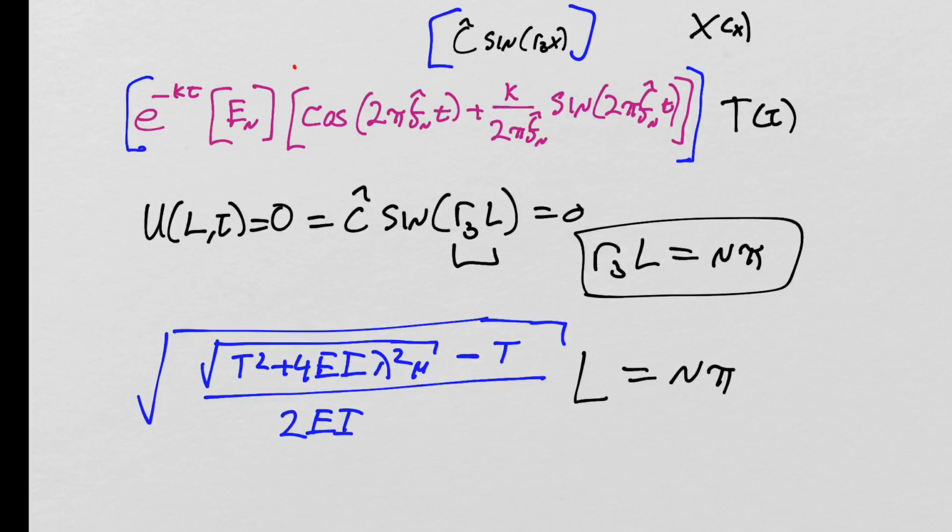So you can kind of see what we've got to do. The goal here is, well, what can we play with, right? Remember, everything's fixed. L is the scale length of the guitar. E is a material property based on the metal of the string. Mu is the geometry of the string and its density, so that's a material property of the string. Tension is set by the guitarist. So the only thing here is lambda. So this whole expression is a way of determining what lambda is, right?